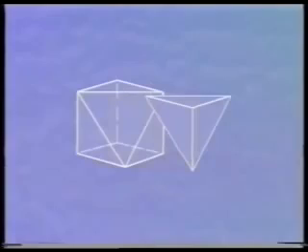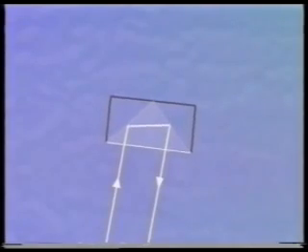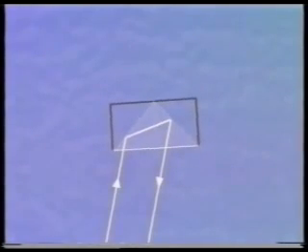The type of reflectors used with infrared instruments take the form of corner cube prisms known as retroreflectors. They are constructed from the corners of a cube of glass which have been cut away in a plane, making an angle of 45 degrees with the faces of the cube as shown. The inner surfaces of the cube are highly silvered, and any wave hitting one of these will be turned through 2 right angles and reflected back along a path exactly parallel to that along which it was transmitted. This will still be the case even if the prism is misaligned by as much as plus or minus 10 degrees, so precise alignment is not necessary.